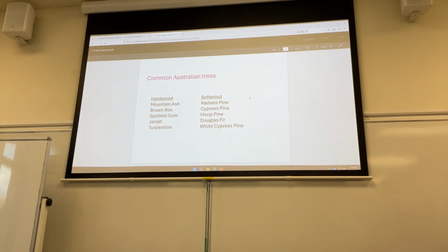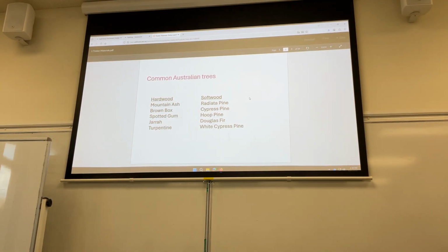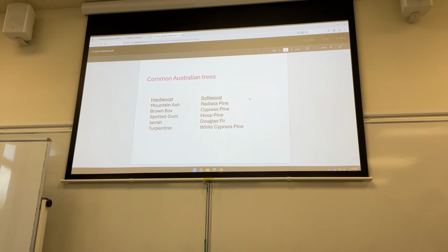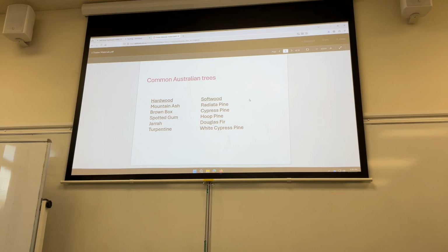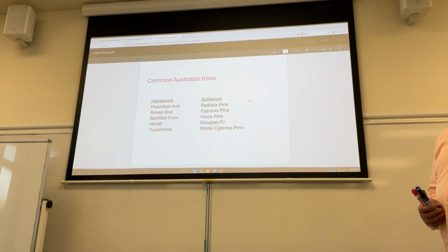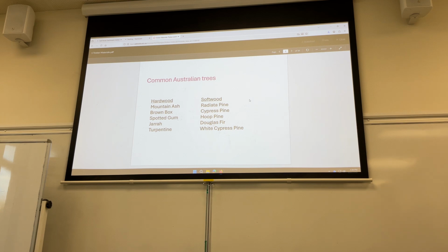So any one of you has attended the practical? You, right? The timber or not yet? So anyone has attended the timber? Yeah, sure. So the type of the timber in the practical is radiata pine. So radiata pine is MGP and F grade in the structural design. But we will lower our expectation, so we consider it as MGP 10 in the lab. Because also in the timber practical, we need to compare the data from the test to the theoretical data. But for the timber, it is very simple. We don't have like Excel calculation or graphs.